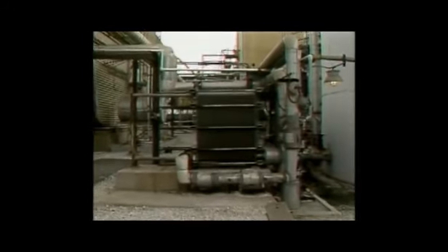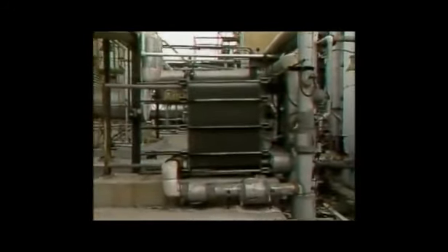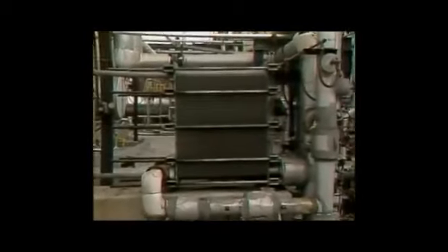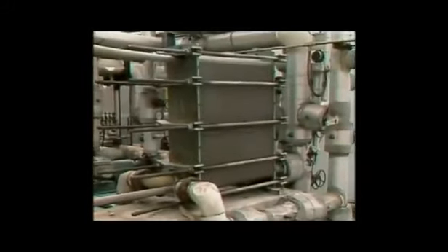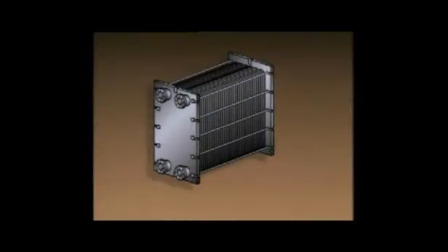Like all other heat exchangers, a plate heat exchanger transfers heat from one fluid to another. This particular plate heat exchanger uses a series of thin metal plates placed back to back to transfer the heat. The plates are arranged so that hot fluid flows downward on one side of a plate, and cold fluid flows upward on the opposite side of the plate. The heat is transferred from the hot fluid through the plate to the cooler fluid on the other side of the plate. To see how a plate heat exchanger works, we'll use this simplified illustration of a counterflow plate heat exchanger.